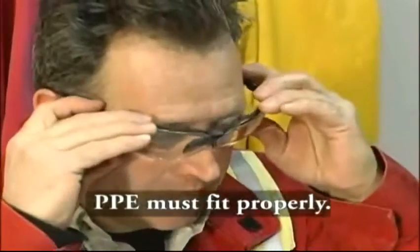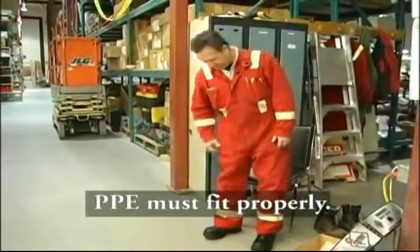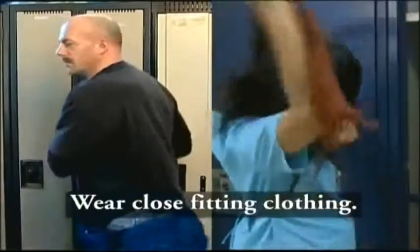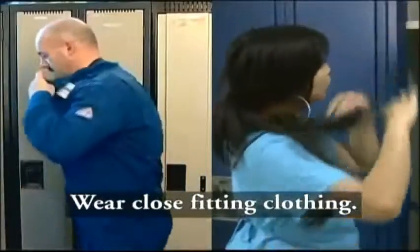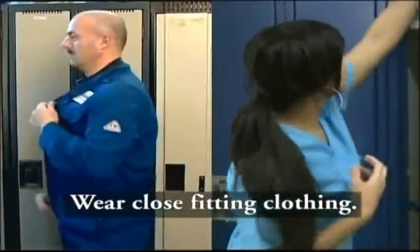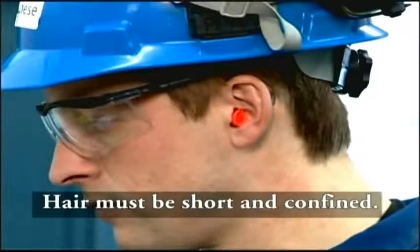Make certain your PPE fits properly. Poor fitting protection can create its own hazards. You must wear clothing that fits close to the body. No bracelets, rings, dangling neckwear, wristwatches, or similar articles. Head and facial hair must be short and confined to prevent getting snagged or caught in tools, equipment, or machinery.